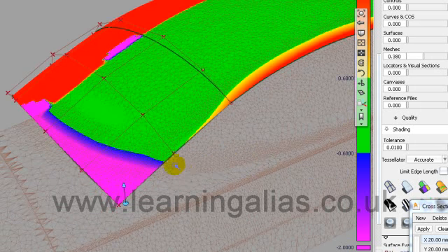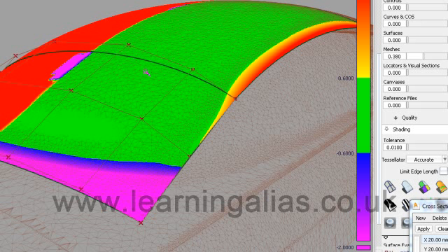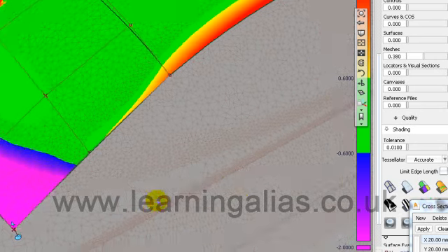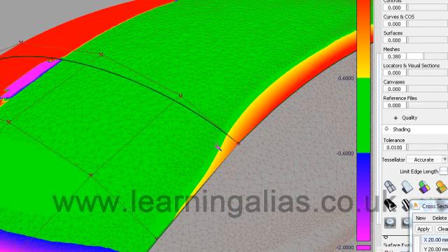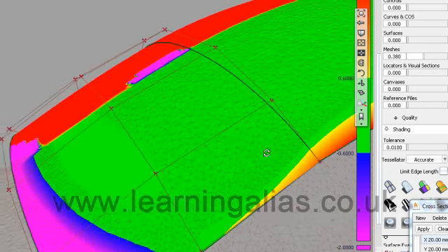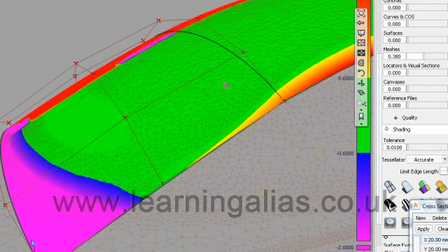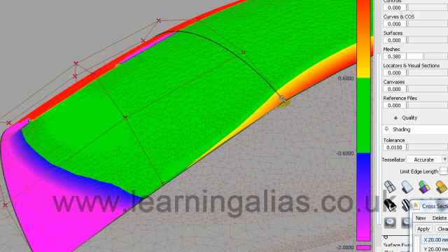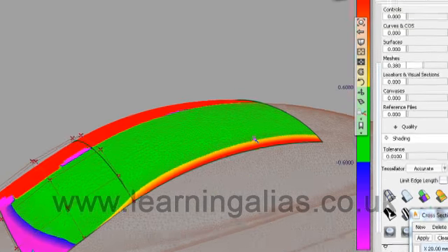at the moment because we haven't increased the degrees in the surface yet to be able to control it accurately there at the boundary. We're concerned with how it sits on the mesh, not what the continuity is there. Probably I'm going to use a freeform blend in here, so I don't actually need these two surfaces to be curvature continuous, but if I did, I would put more degrees in here and then direct model using a locator here and the information window.